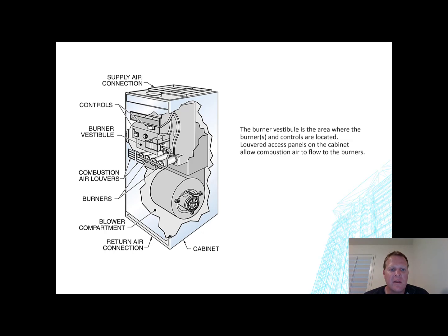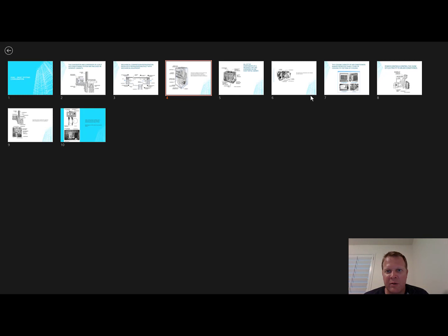We've got the air going up through this space right here, out this duct right here to the house. The combusted gases being inside here, coming out the flue. The combusted gases heating up this metal of this heat exchanger, and the air that's passing over it from this blower getting hot, right? Talked a lot about that. And then we got into refrigeration.